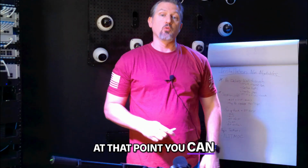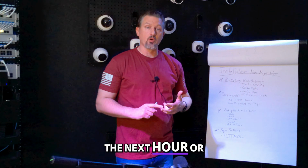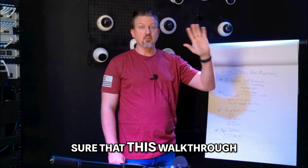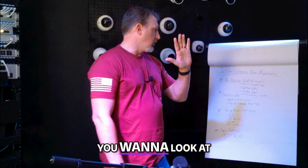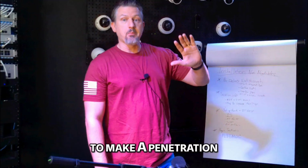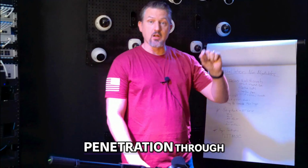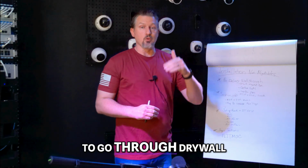At that point, you can find your routes. But you want to take the next hour or 2 hours and make sure that this walkthrough is done thoroughly. You want to look at your routes. Is there a place that we're going to have to make a penetration? What are we going to have to make a penetration through? Are we punching through sheet metal? Are we going to have to go through drywall?